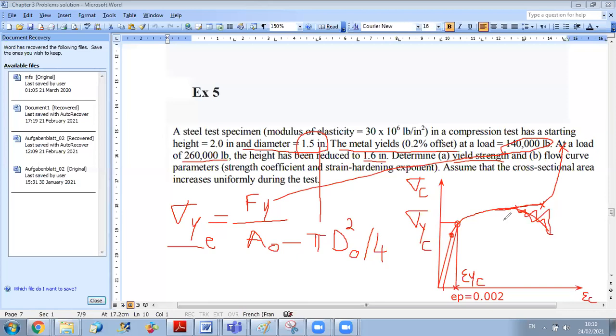Now this part doesn't matter for the analysis, because we are just talking about the elastic region and how to determine the yield point. Okay. But in case they ask us to represent the total profile for the engineering curve, we have a point of inflection. And if you remember why we have this effect, when we did the analysis, first when we go to the plastic region, it will be easier to deform. So for a certain period, the slope will decrease. But after this, the slope will begin to increase.